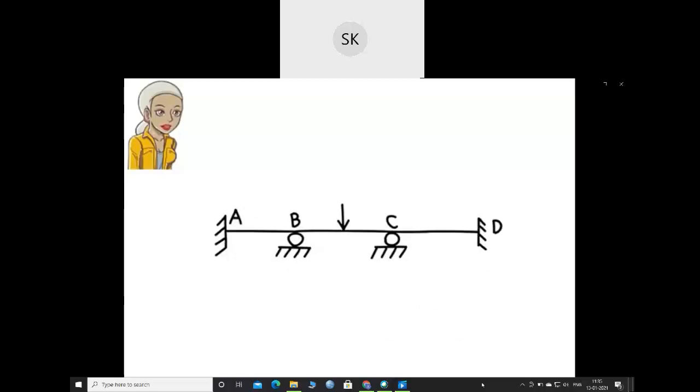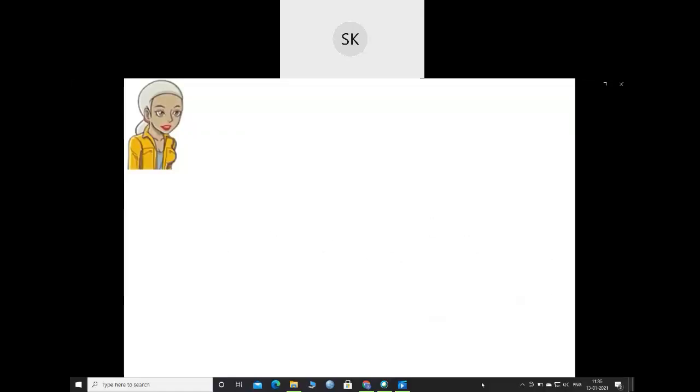Finally, the elastic curve for this beam looks like this. An alternative formulation for this problem involves decomposing the trapezoidal load into a rectangular load and a triangular one, such that if we add the triangle to the rectangle, we get the trapezoid.